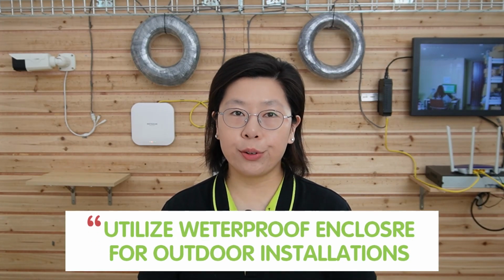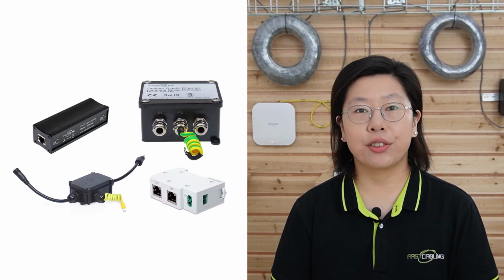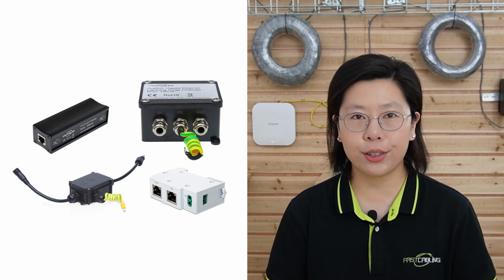When extending your IP camera network, you should consider these tips for optimal performance. You can utilize a waterproof enclosure for outdoor installation, protecting equipment from harsh weather conditions. Alternatively, offer an outdoor PoE pass-through switch designed to withstand outdoor environments. Install a surge protector to safeguard PoE equipment from power surges, particularly crucial in outdoor setups where the risk of lightning strikes is higher.